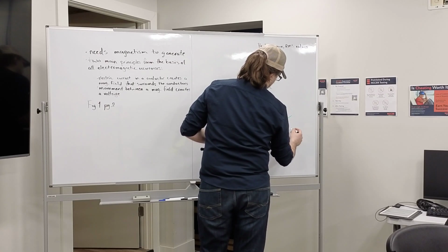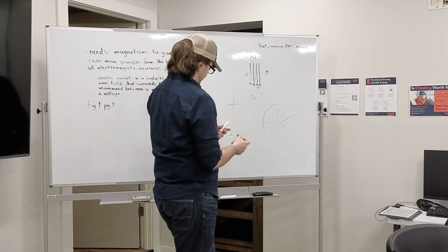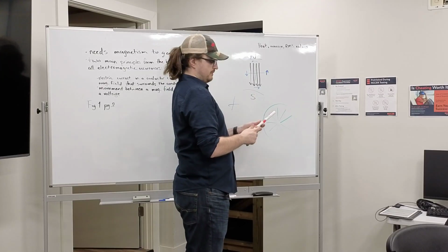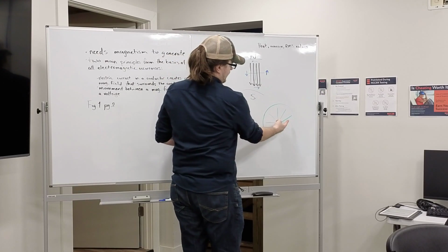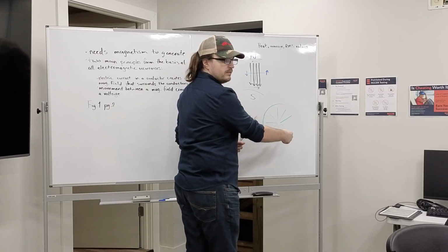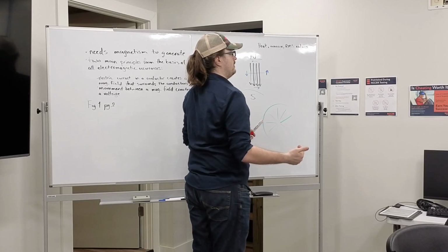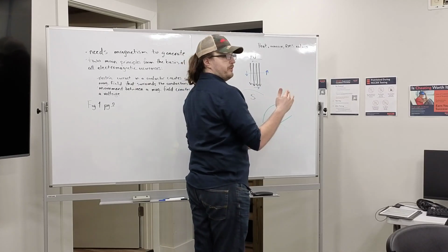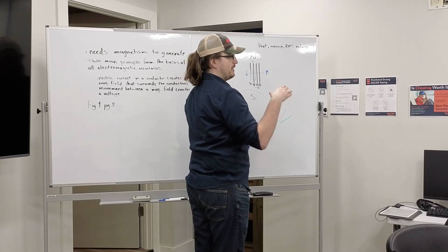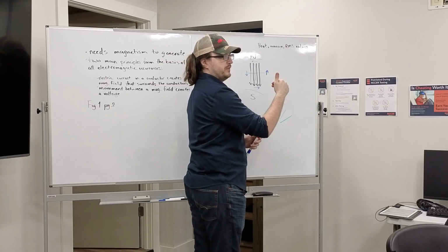Okay, I was confused because I was looking at it from this angle, but y'all are looking at it from like that. So look over here. The conductor travels in a circle. The direction in which it's moving at any given moment, you only look at it at the very end, because that's the part that cuts across the magnetic field.